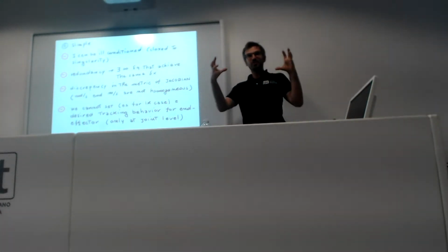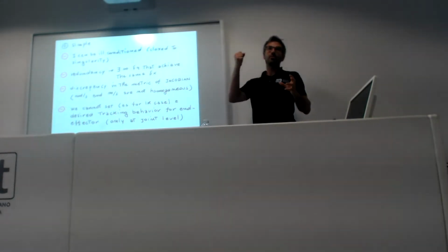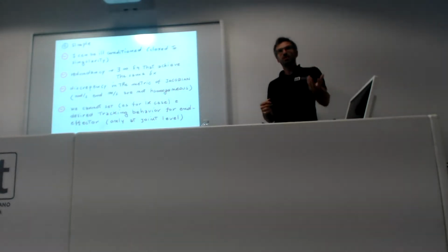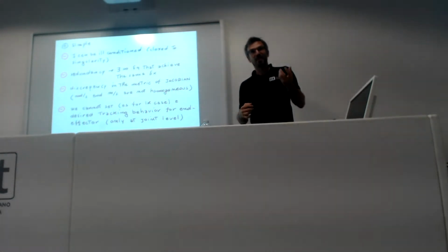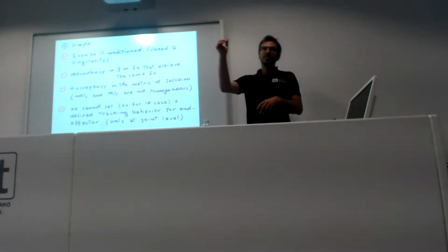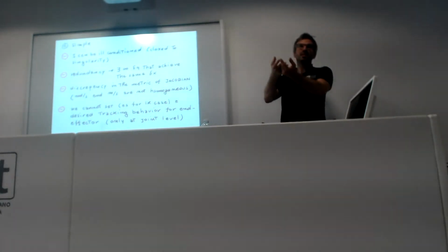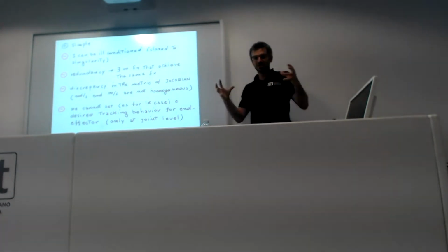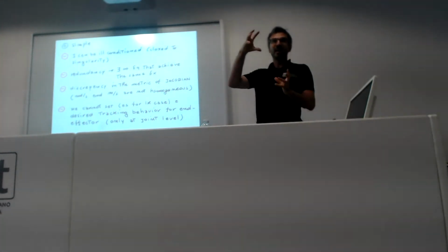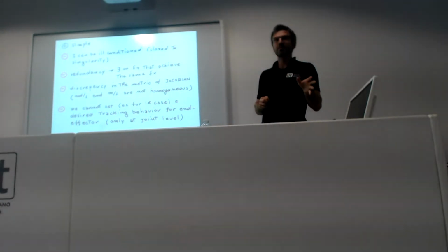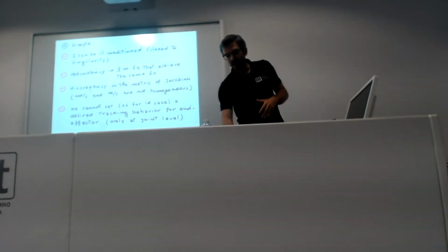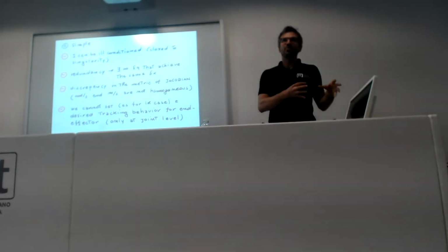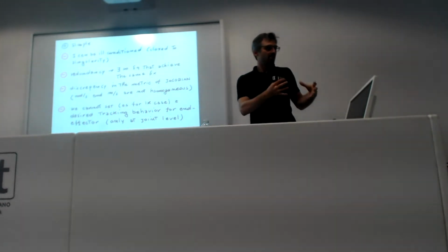And this ellipsoid will change with the end effector configuration. So even if you use the same gains at the joints, because the Jacobian is nonlinear and configuration dependent, the effect of these gains on the dynamics at the end effector is an ellipsoid, and this ellipsoid changes shape and even orientation. So it's not very nice, because ideally at the end effector we want to be sure that our stiffness, for example, is isotropic.